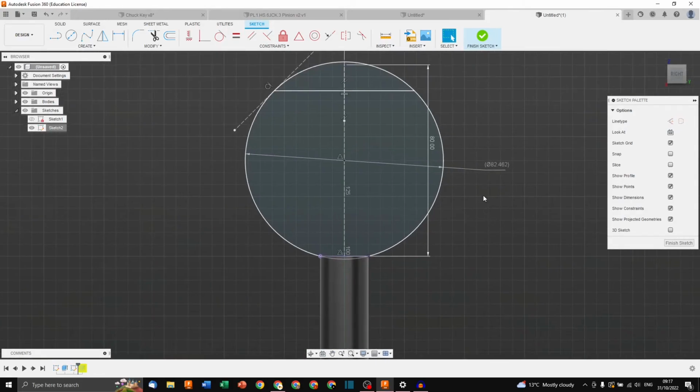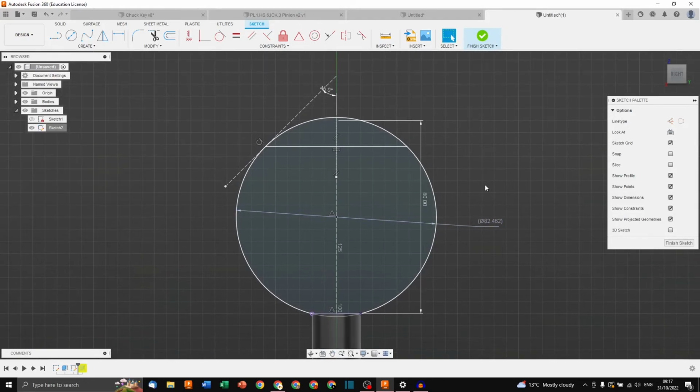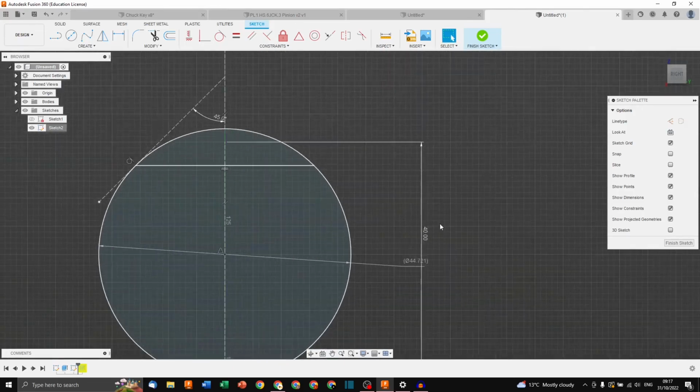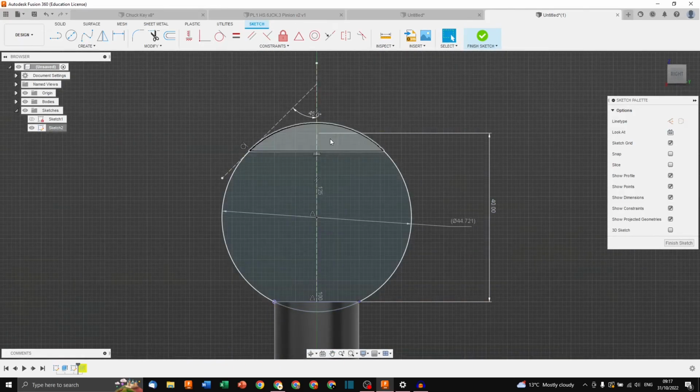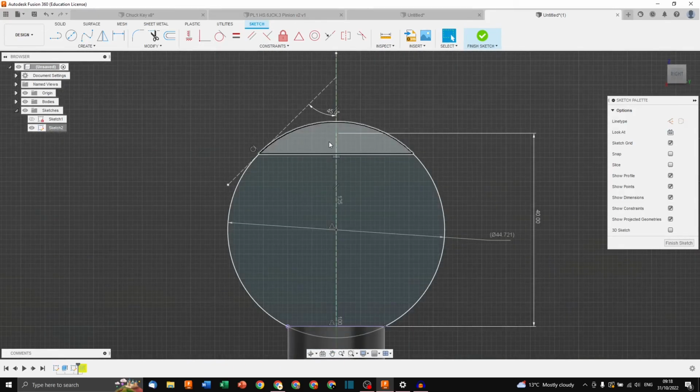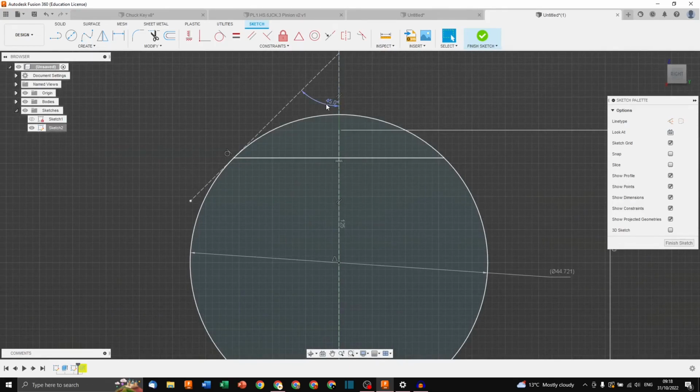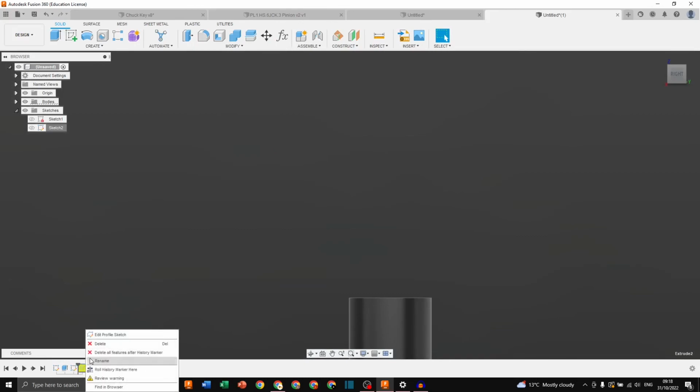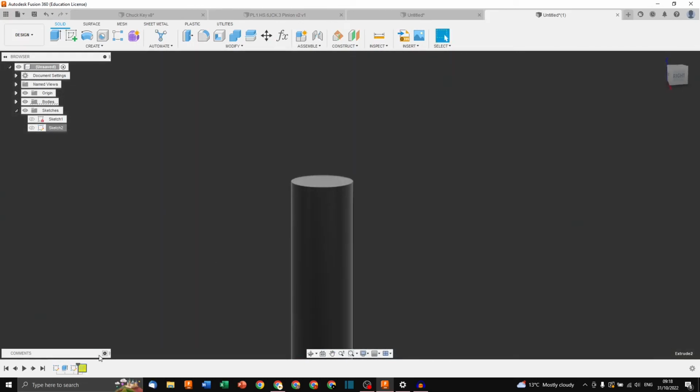It's good because I make mistakes, and I'm the one teaching. It's showing you just how complex this really is. To do a perfectly constrained sketch is really complicated. It's not trivial at all, and people think that it's just a stupid sketch, but it makes a big difference. When you've got a good sketch, like our sketch here, that will always be at 45, you can now extrude this. So when you break an extrude or break something else in the model because you made a bad sketch,